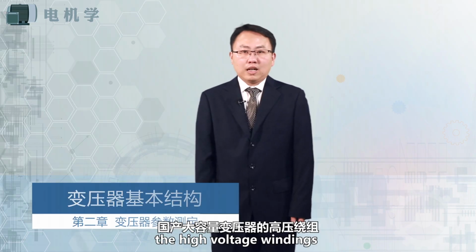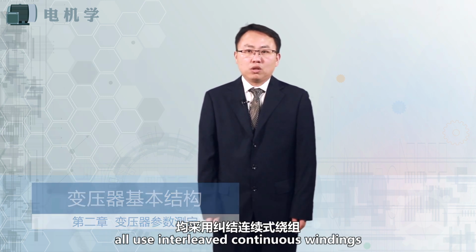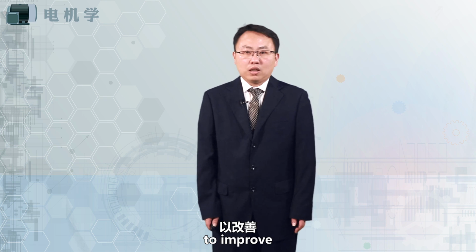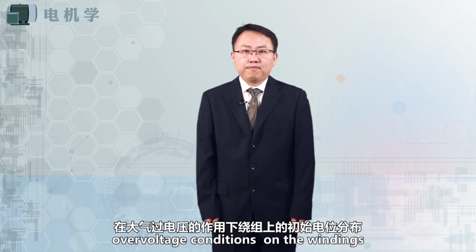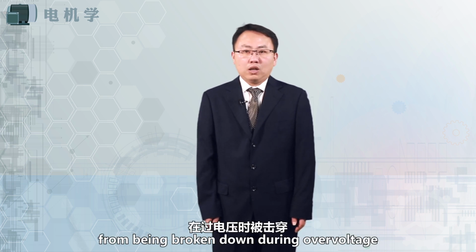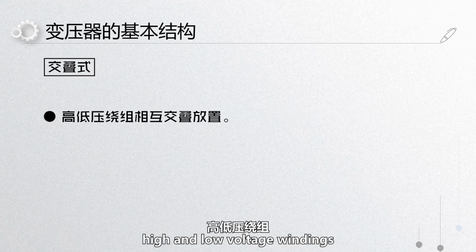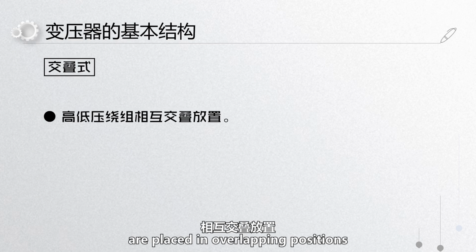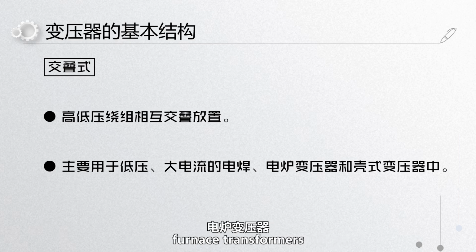In recent years, the high voltage windings of domestic large capacity transformers all use interleaved continuous windings to improve the initial potential distribution under atmospheric overvoltage conditions on the windings, to prevent winding insulation from being broken down during overvoltage. Overlapping type high and low voltage windings are placed in overlapping positions and are mainly used for low voltage, high current welding, furnace transformers, and shell type transformers.